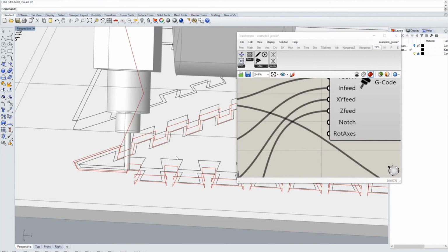For example, for cutting a pre-pass, you might want to use a thicker tool to cut a first pass, which cuts faster. And then you do a second pass where you use a smaller tool and it's going to cut all of these little notches.